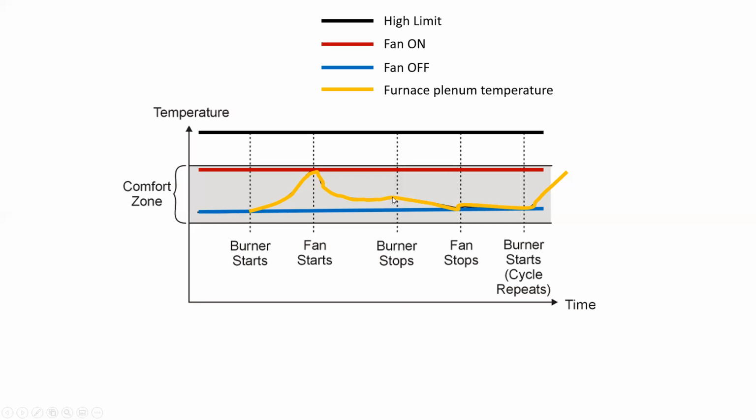At this point, the fan continues to run until the temperature in the plenum drops down to the fan off temperature, at which point the fan stops. At this point, we're again ready to continue on another burner or heating cycle.